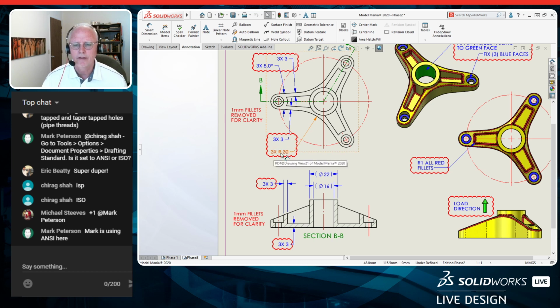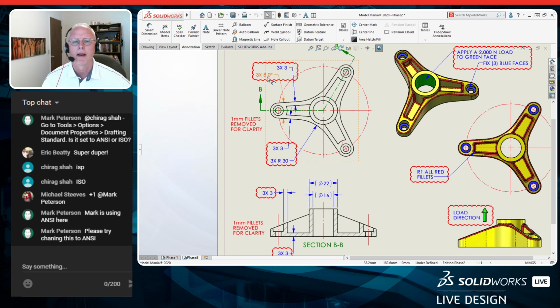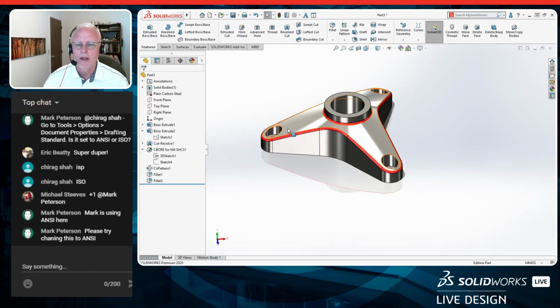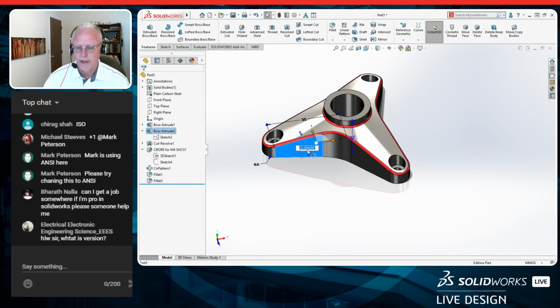So we have that. This fillet changes now to 30. Okay, that doesn't seem too bad. And then this angle changes to 8. So remember when we sketched that out before, it was wider, and came in here. So that's going to go down to 8. Let's do the 8-degree change here, and then we'll also do the offset there. So I'm going to come back to my part, and we'll do our 8. Let's see. Make that 8.